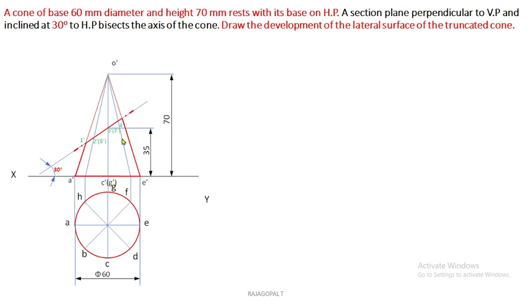Next we have O dash E dash, O dash F dash, and O dash D dash, which give 4 and 6. I don't have sufficient space, so I represented only 4 dash. Finally it is 5 dash on O dash E dash. So we know that in radial line development, we have to shift all the section plane cutting points to the end generator, either O dash E dash or O dash A dash.